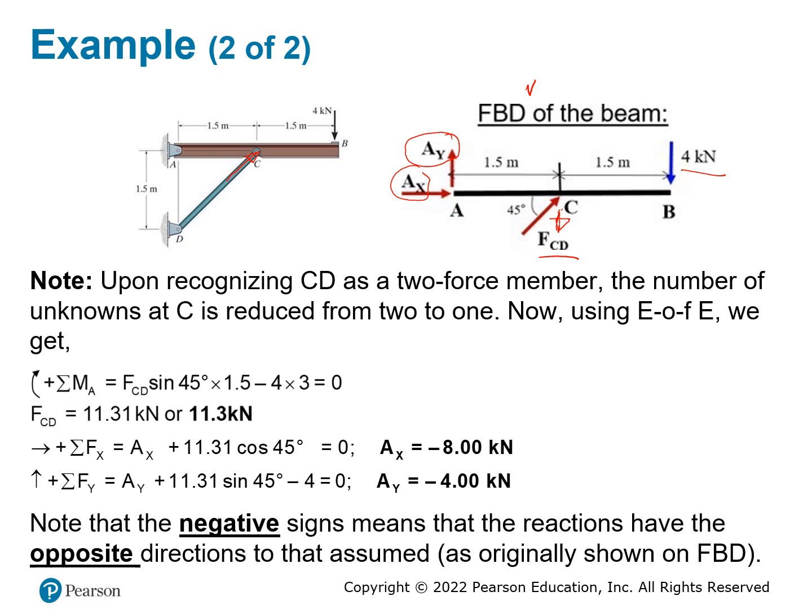So once you have all these together and you are ready to solve the problem, you just write down the equations of equilibrium. The summation of Fx and the summation of Fy are very simple, and you can simply do that by yourself. But to solve this problem, the easiest one to start with is actually the summation of the moment. When you do a summation of the moment, I normally pick the reference point where most of the forces act that you don't have the value for.